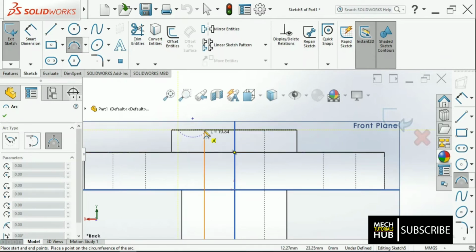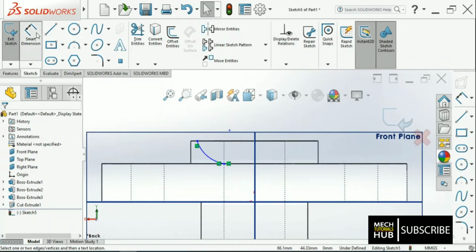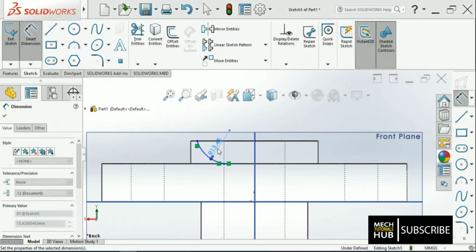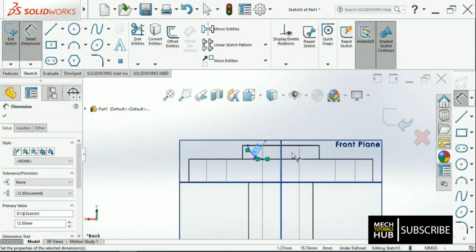Wherever this particular 24 dia vertical is, I'll end my curve there, and place it something like this roughly. Later I'll give dimensions. Done. Now let us fix this radius. This radius is supposed to be 12, as given in the question. This is done. Now it is perfect. Okay, no need to do the other side also.